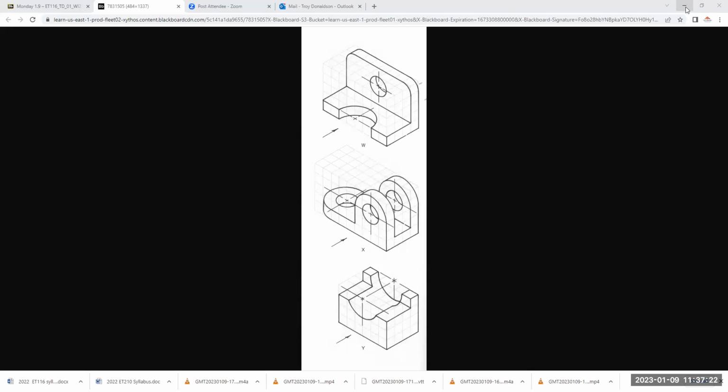Now, how do I check it? How do I know that's 1/8 inch? If you're in paper space, I can measure it, right? Because this is in model space. That's 1/8 of an inch, supposed to be. So I can literally, in paper space, measure something that is in model space. I can't grab points, but I can do this. I can go from there to there. It's supposed to be 0.125, so it's probably rounding it. It's 1/8 inch for sure on the paper.